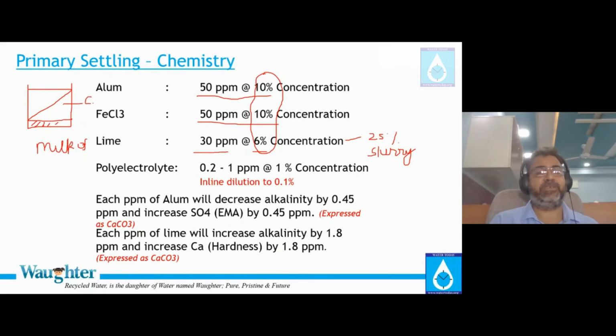Actually, this liquid which is transparent, crystal clear is calcium hydroxide, Ca(OH)2. I need this material for pH adjustment. I do not need this sludge called calcium carbonate. Getting my point? This sludge is calcium carbonate. This sludge is gypsum, calcium sulfate. I don't need it. For pH adjustment, I need calcium hydroxide. So a good wastewater treatment designer will have something like a lime silo and all that.